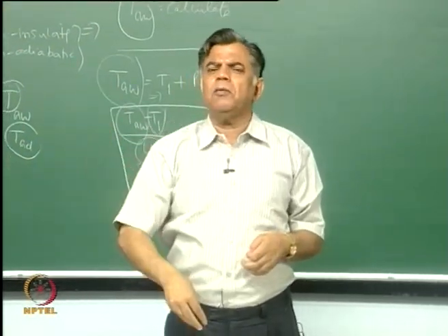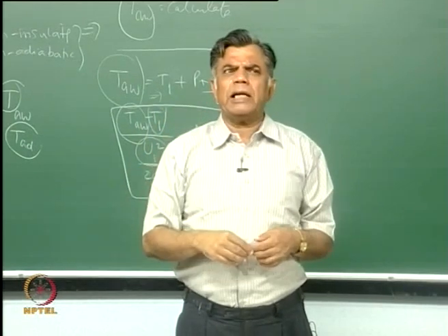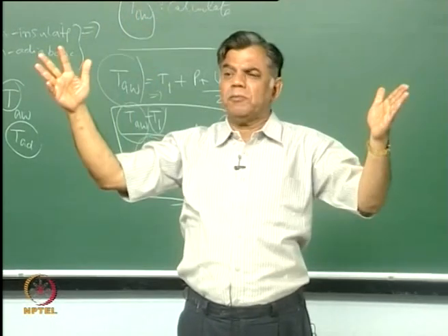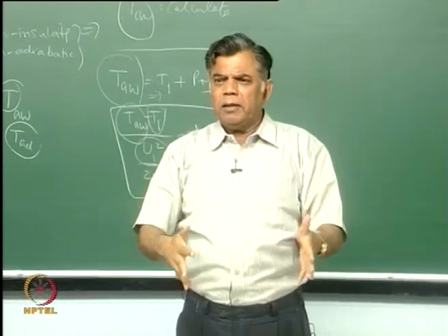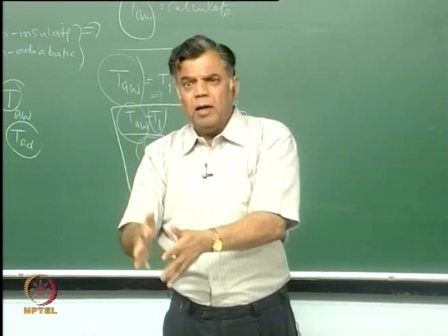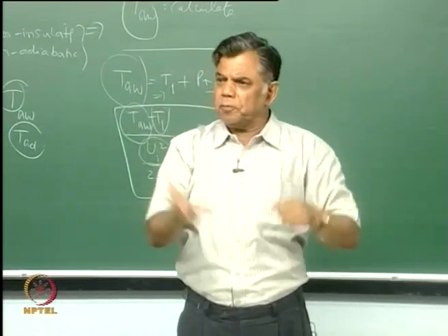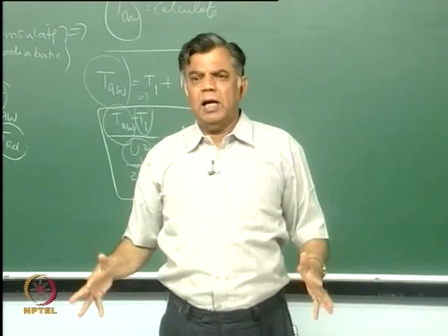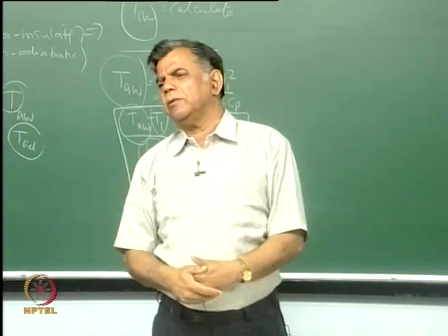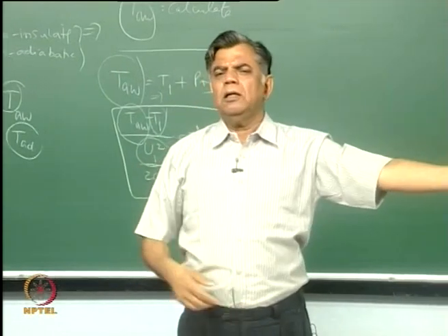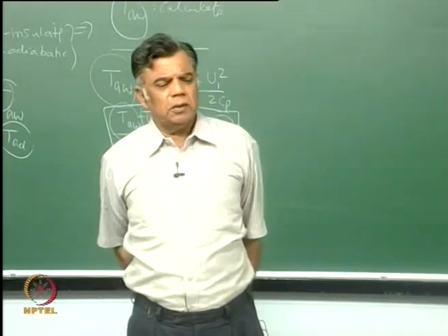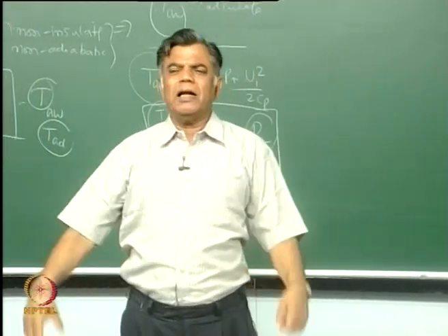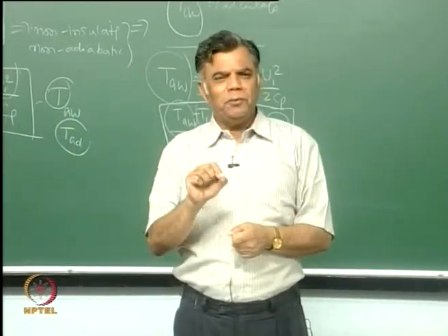How did this come up? How was the rate of heat transfer calculated? q is equal to minus k dT by dy. That is why, in the beginning stage, I said physics-wise, I want for my heat transfer dT by dy at y equal to 0. For me to get that, I have to have the entire temperature profile. For you to have the temperature profile, you have to have the energy equation along with the boundary conditions, and that comes from nature, which is the first law of thermodynamics. So from nature to the rate of heat transfer in an adiabatic or a non-adiabatic situation, you can understand,